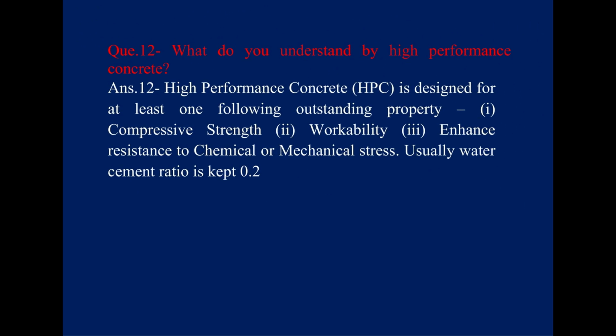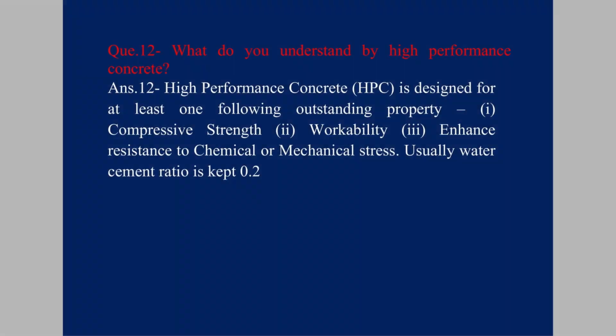Question: What do you understand by high performance concrete? Answer: High performance concrete, HPC, is designed for at least one of the following outstanding properties: compressive strength, workability, or enhanced resistance to chemical or mechanical stress. Usually, water-cement ratio is kept at 0.2.